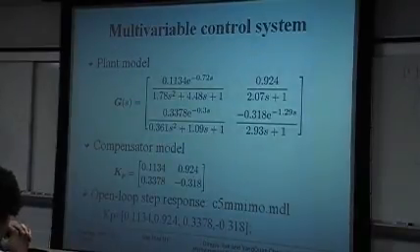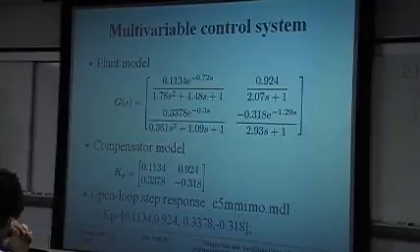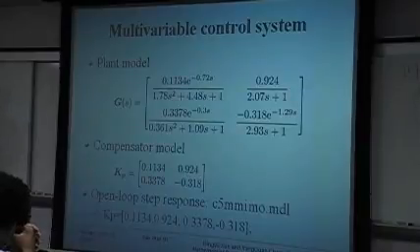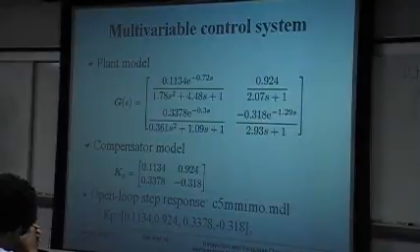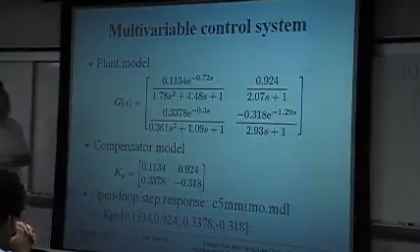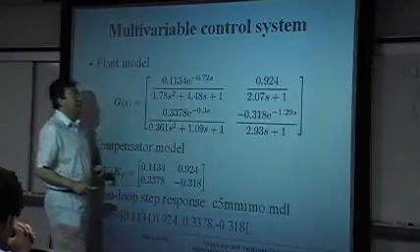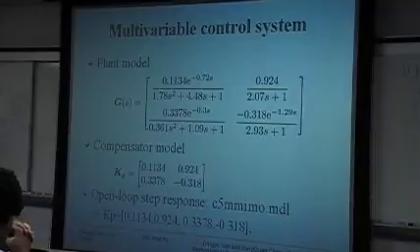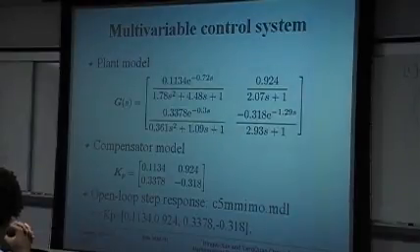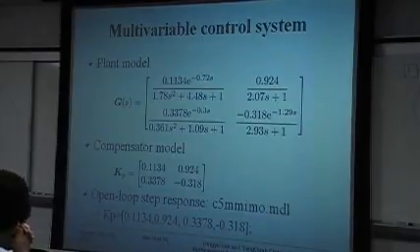However, if the system is preceded by a matrix here, Kp, then we cannot multiply them together like this, because there are delay terms on different sub-transfer functions, and the delay constants are not the same. So we cannot use this kind of multiplication to get the overall model. So we cannot use LTI objects to solve this kind of problem.